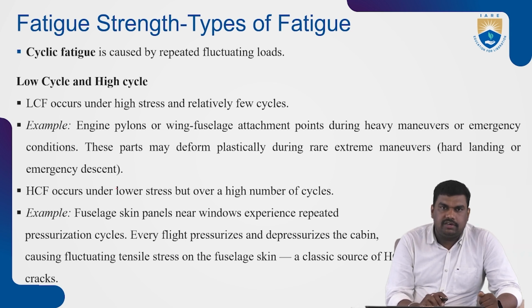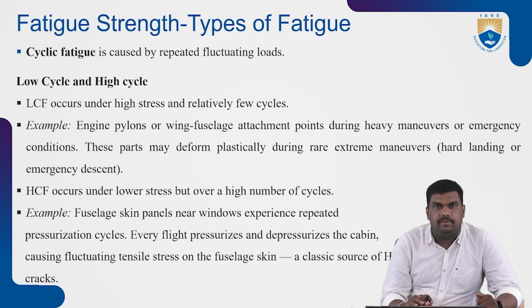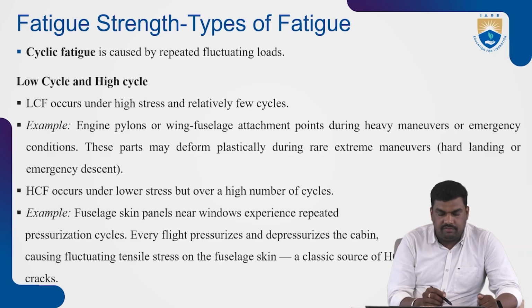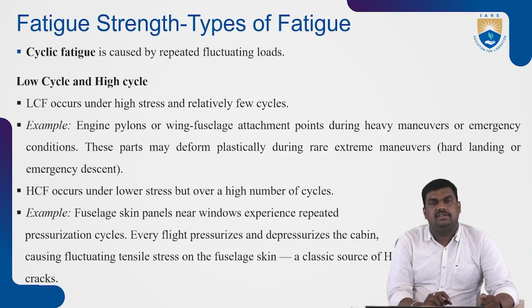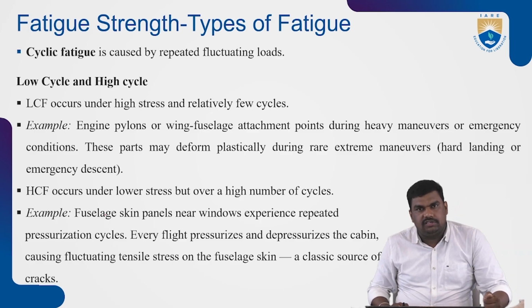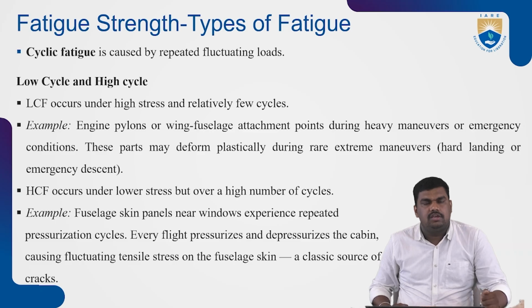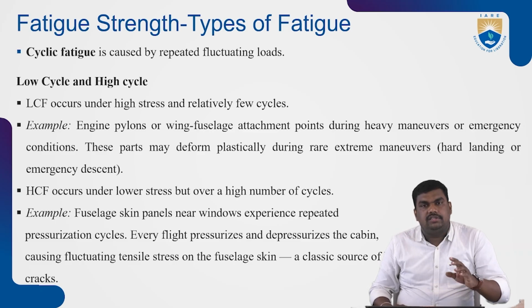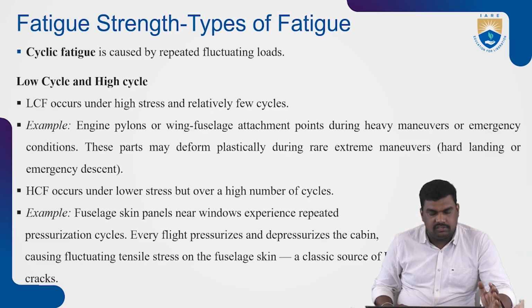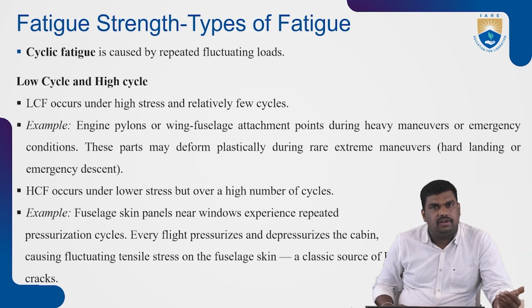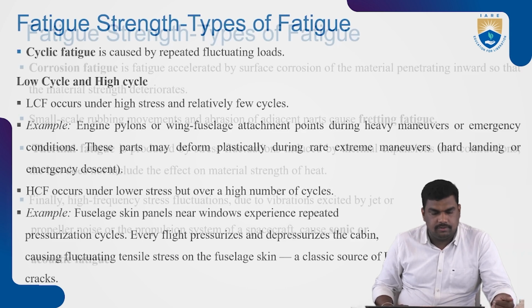High cycle fatigue occurs when the stress is less, so the number of cycles will be more. For example, the fuselage skin panels and areas near windows experience repeated pressurization cycles, pressurization and depressurization of the fuselage during takeoff and landing. It will experience axial loads on the fuselage skins, but comparatively very low stress compared with other aircraft stresses. So with low stress, you will have a high number of cycles.